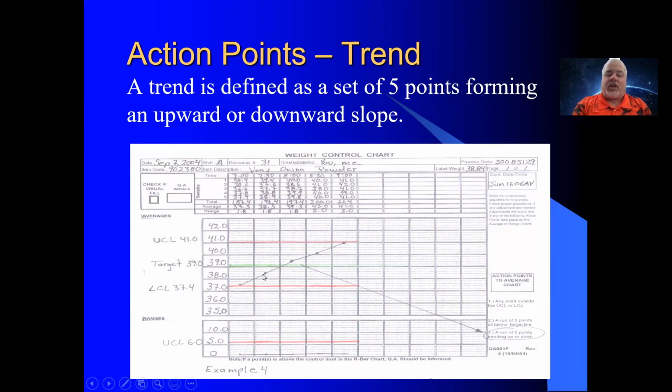Just this one's a little higher average, this one's a little higher average. That's saying there's a trend that might be a problem. Is there something going on with our raw product? Is there something going on with our packing machinery, our scales, whatever? What's going on? And you want to explain this. It could be just a fluke. You run these machines long enough, and every one of these is going to happen.